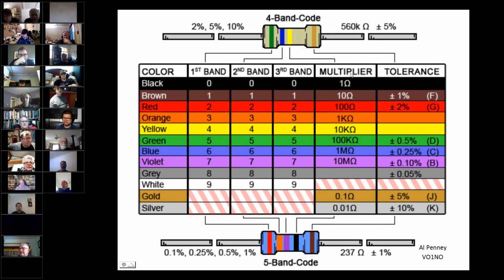So we've got 5, 6, but we don't know if that's supposed to be 56, 560, 5,600, or even more. So we go through, and the multiplier here is yellow, so it's 10 k ohm. K means kilo, which means 1,000. So we multiply the 56 by 10,000 ohms. That gives us 56 times 10,000, which is 560,000 ohms. We've got k ohm. Okay, so that K means kilo. We'll talk more about that in a later chapter.